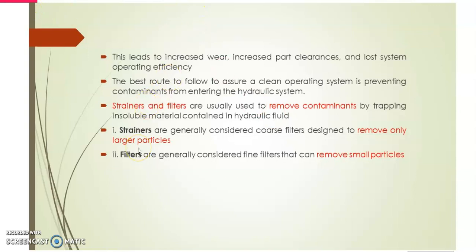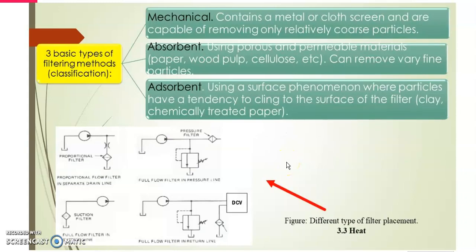Strainers are generally considered coarse filters designed to remove only the large particles. Strainers are constructed of a wire screen. They rarely contain openings less than 100 mesh. Filters are generally considered fine filters that can remove the small particles.